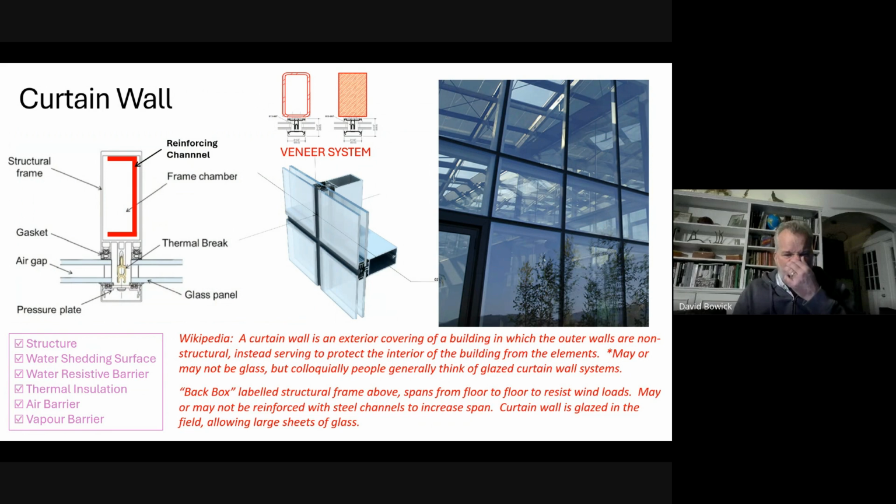Okay, here's the one you're going to deal with most frequently. This is curtain wall. Curtain wall consists of three components. There's the glazed panel. Remember that any glazing system is a perfect barrier, drain joint. Curtain wall consists of the glazed panel, the structural frame, which is an aluminum extrusion, and a cap and pressure plate on the outside.